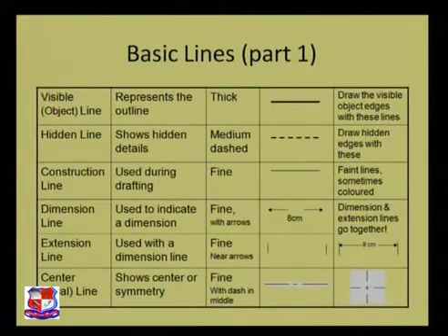Now we will see the center line. I have drawn a circle, but if I do not draw a center line, then I cannot specify the circle's center. Of course, if I am drawing manually using the compass, there would be a spot of the compass on the paper. But if I have made several arcs in the same drawing, then I may be mistaken using those spots. So we need to specify the center of the circle.